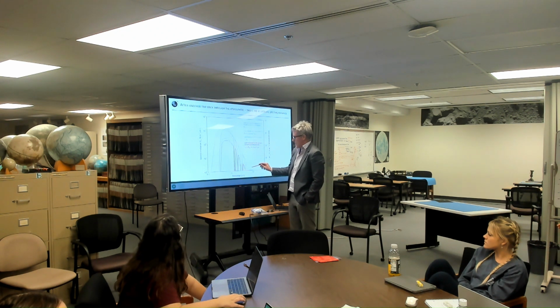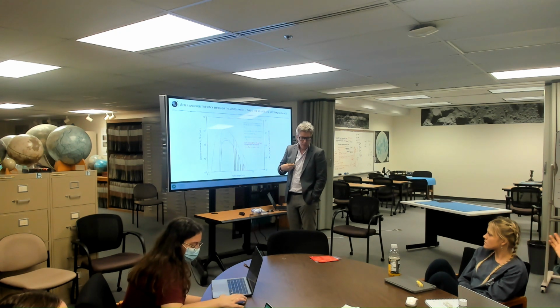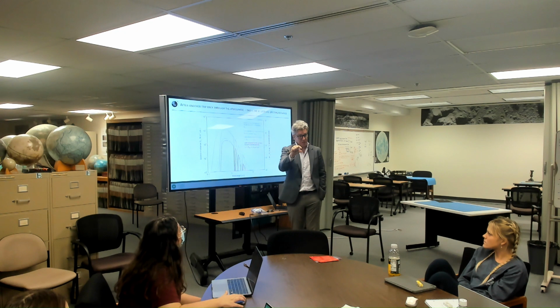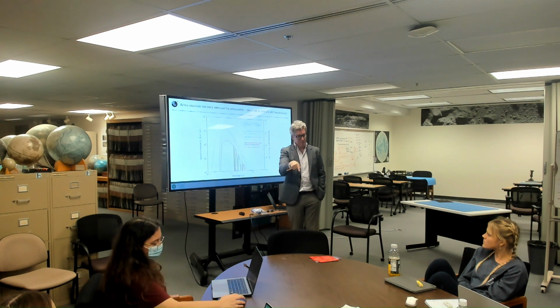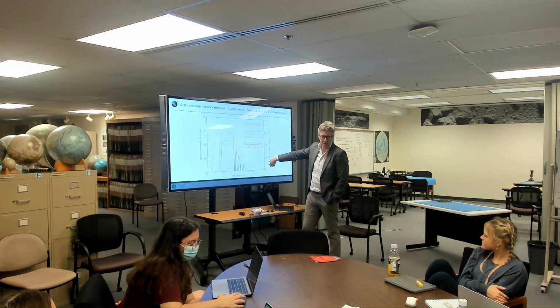When you sense it remotely, you can't see the IR unless you have the instrument to look at it. So you need a detector that has a band gap which is narrow enough such that you can free an electron using infrared energy rather than visible energy. So far we are not talking about instrument design at all.